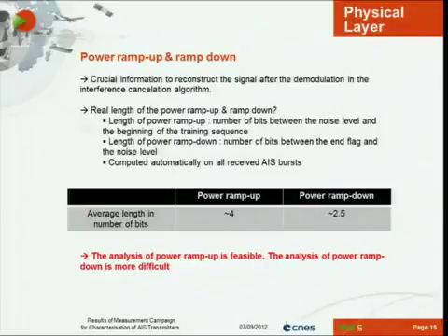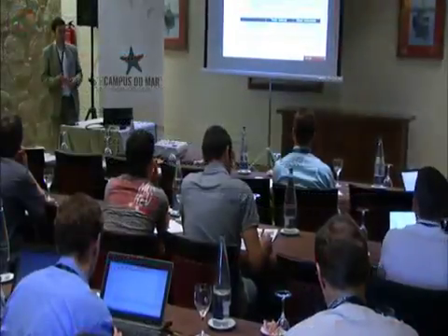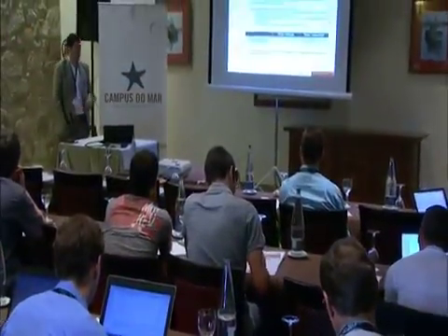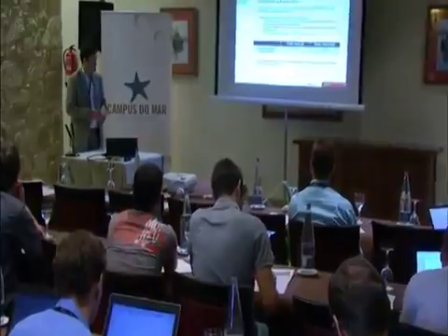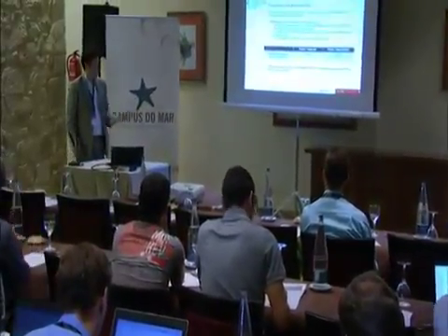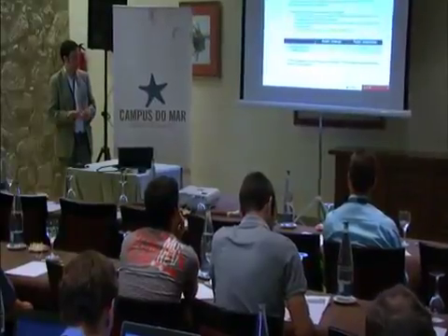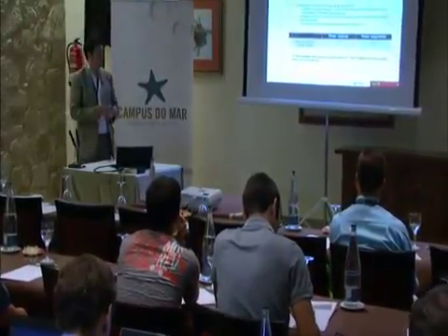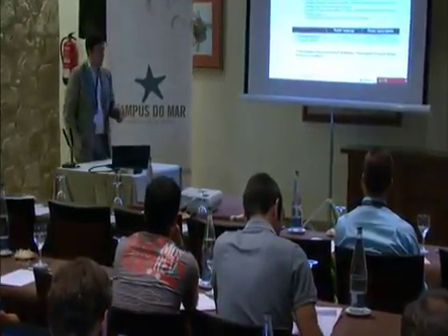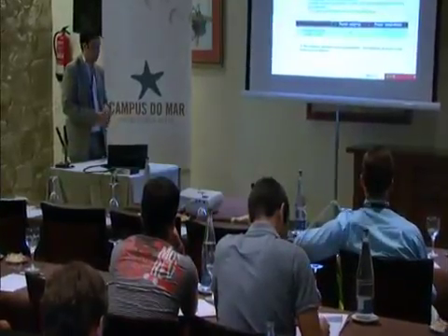The average length of the power ramp-up is about 4 bits, and for the power ramp-down portion, it's about 2.5 bits. So the analysis of the power ramp-up is feasible. 4 bits is enough. It's more difficult for the power ramp-down, so we will focus only on the power ramp-up portions.